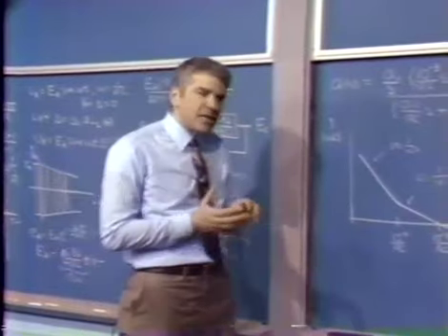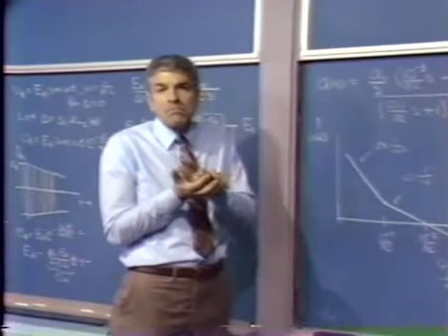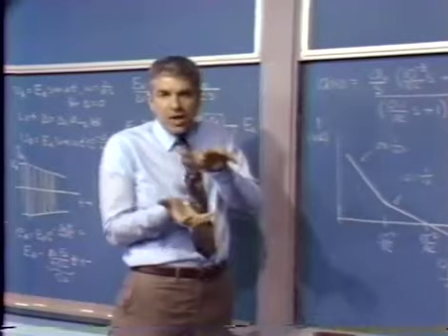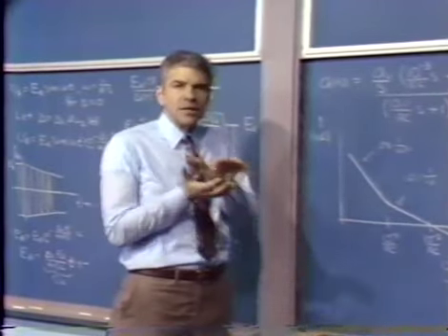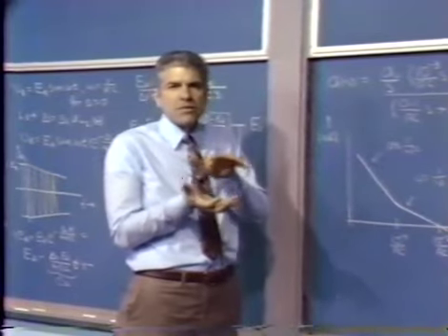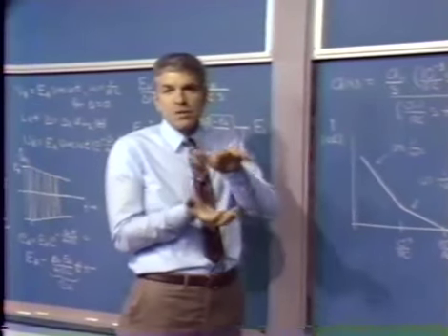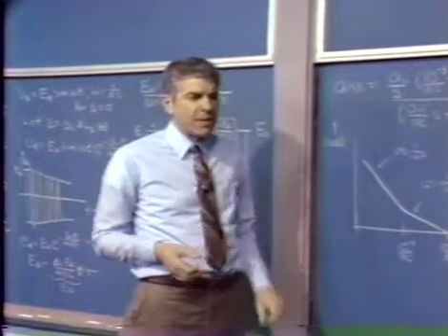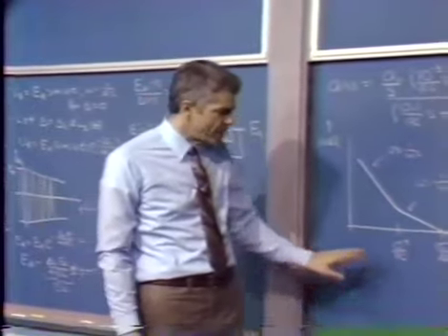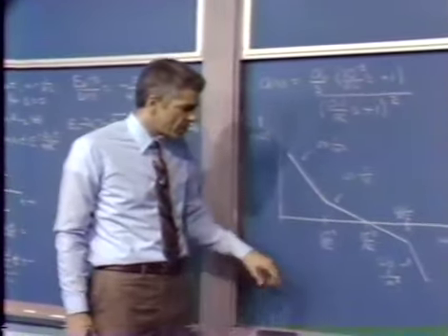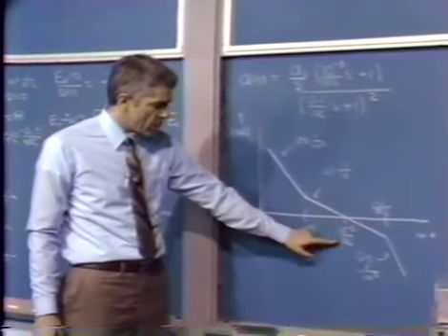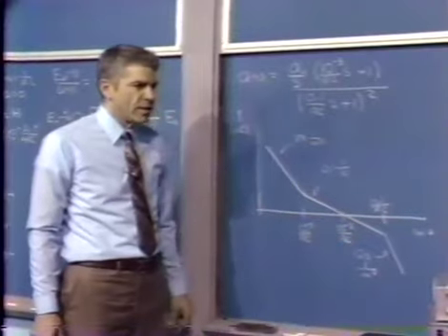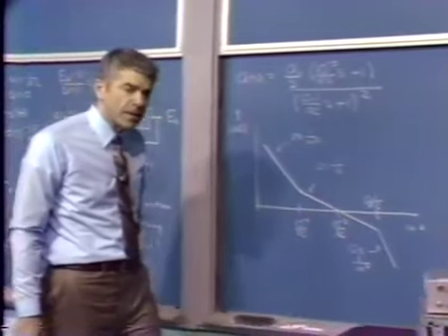However, it's possible in some applications that we might want to make command changes in the amplitude of the oscillator. And if we do that, then we'd like to have a reasonably high crossover frequency in the amplitude control loop so that we get fairly fast response to commanded changes. I haven't tried to push that at all in the system we're going to demonstrate. What we'll do is really design for a nominal crossover frequency that's 1/100th of the oscillating frequency.